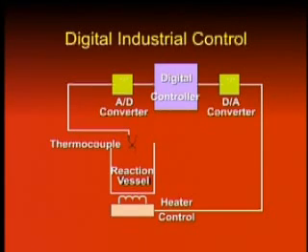So the temperature of the vessel is monitored to control the chemical reaction. As the temperature of the vessel rises, the heat has to be reduced by a proportional level. An electronic temperature sensor converts the temperature into an equivalent voltage value. The voltage value is continuous and proportional to the temperature.